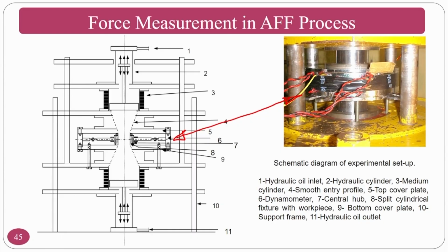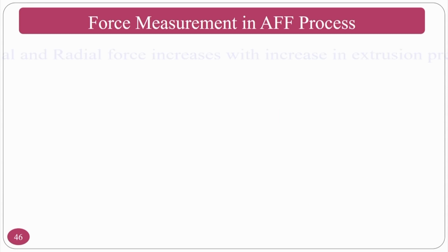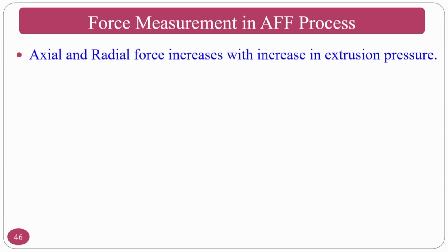Whenever the medium moves in the workpiece region, it exerts a certain radial force and a certain axial force. Those can be measured by the disc type dynamometer. Force measurement: axial and radial forces increase with the increase in extrusion pressure. These are some of the observations by Professor Gorana and Professor V.K. Jain. So as you increase the extrusion pressure, what will happen?